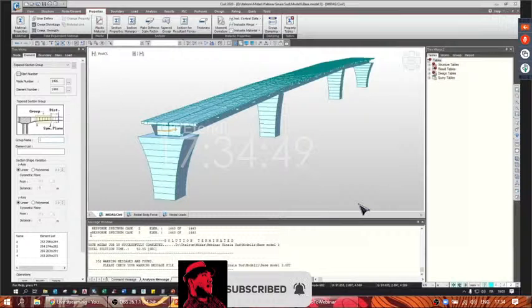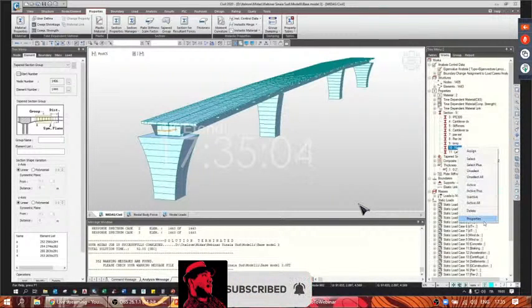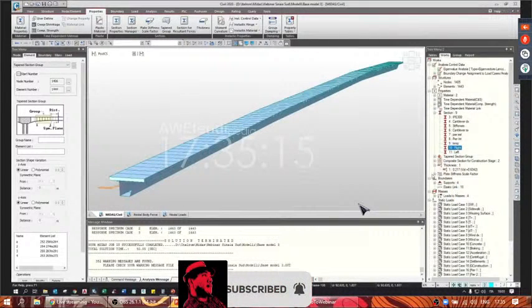In this model, we used a non-common composite section that has been created with a specific tool of MIDAS, the section property calculator, and then imported as a sec file. Here you can see, for example, the section import. Here now we can see how it appears. This is the main beam, one of the two main beams.